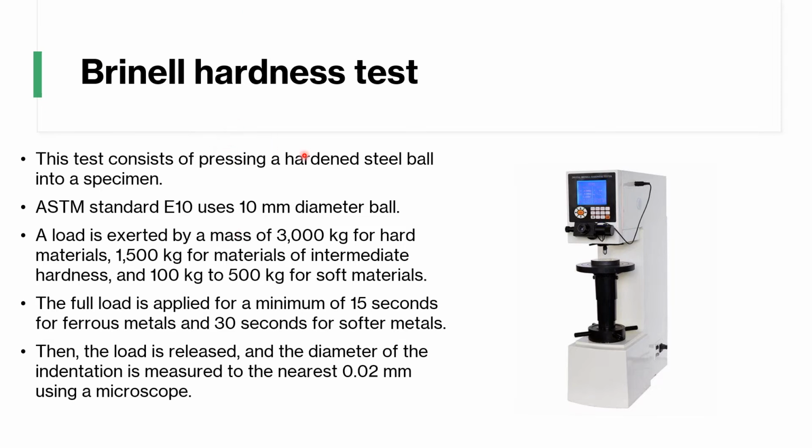So if you think about the Brinell hardness test, all you have to remember is you put on a load to a specific size of your specimen, and then you pay attention to different materials, and then pay attention to how long you have applied that load, and then you look for the indentation, okay, and then measure it. That's it.